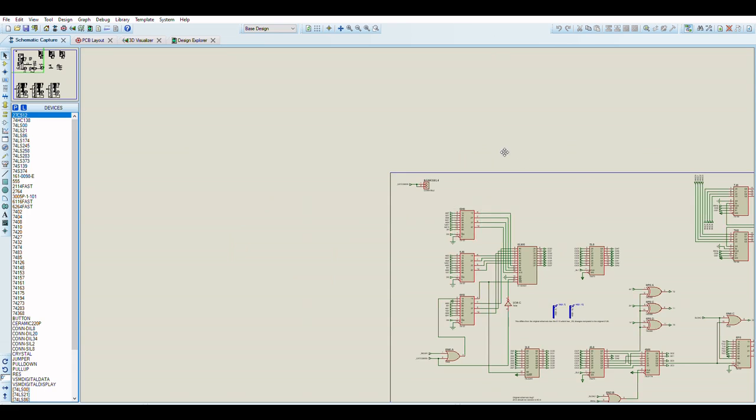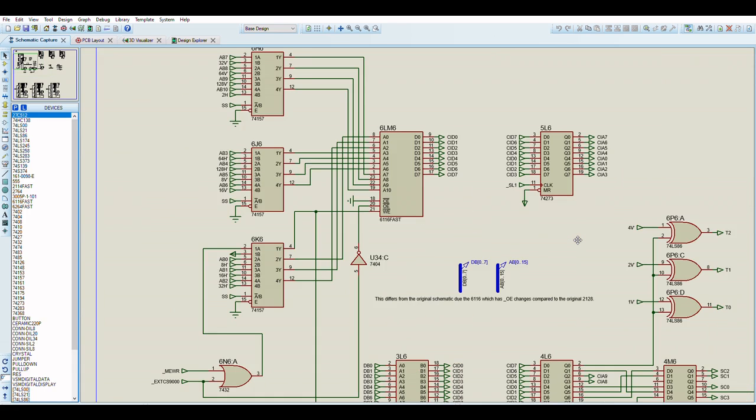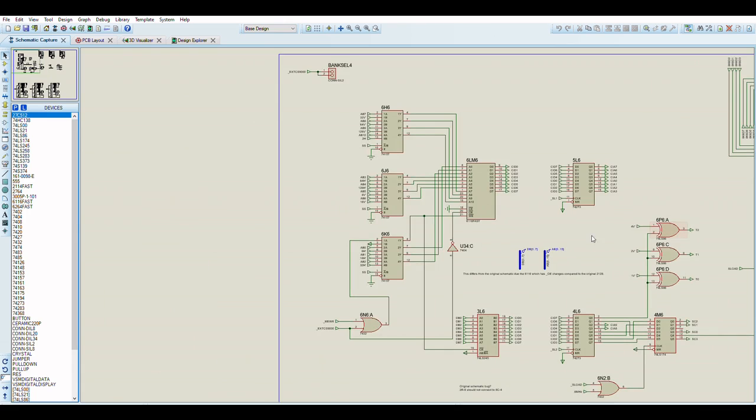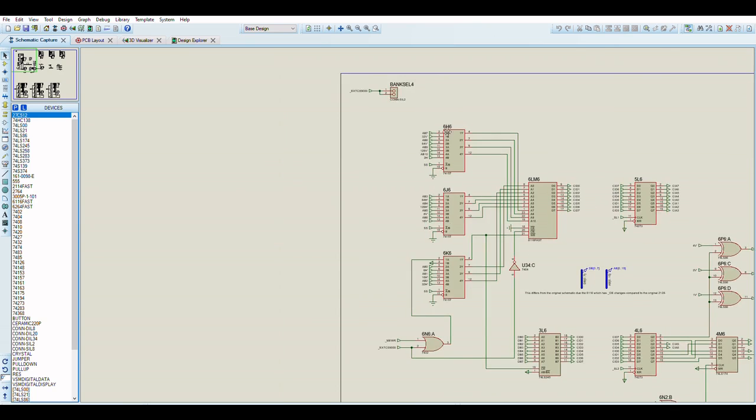The rest of this logic here is to deal with handling whether or not you are trying to write data into the character screen memory, or if you're trying to read data from the character screen memory. And the character screen memory also contains the color memory up in a different area of the memory, but it's all stored in the same RAM. So that's just using that signal here for RAM or color definition.